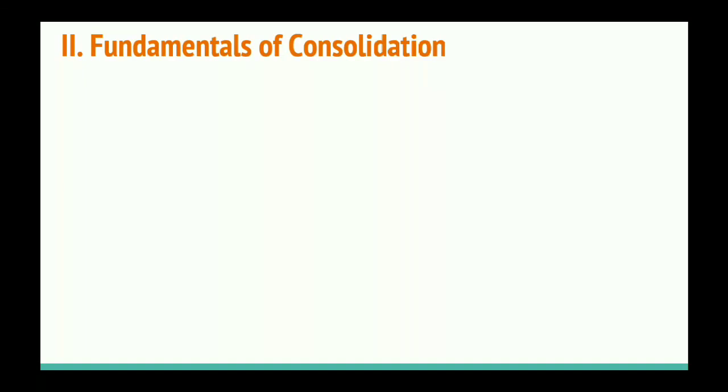Fundamentals of consolidation. So what is consolidation? The compression of saturated soil under a steady static pressure is known as consolidation, and it is entirely due to the expulsion of water from the voids. The fundamentals of consolidation we can easily understand by the spring cylinder model.